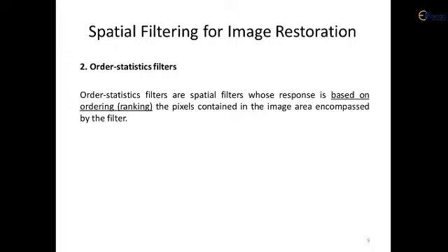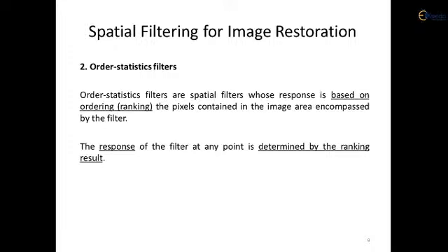I have already made it clear that these belong to the spatial domain. The response is based on the order, which is also known as the ranking. So the response of this particular filter at any certain point is determined by the ordering or the ranking result only, hence the name. And this type of order statistic filtering is best suited for unipolar or bipolar noise, which we just dealt with, also known as salt and pepper noise.